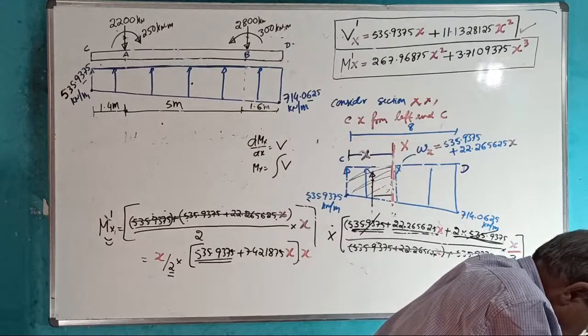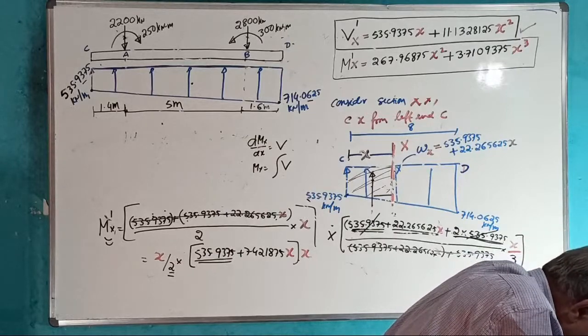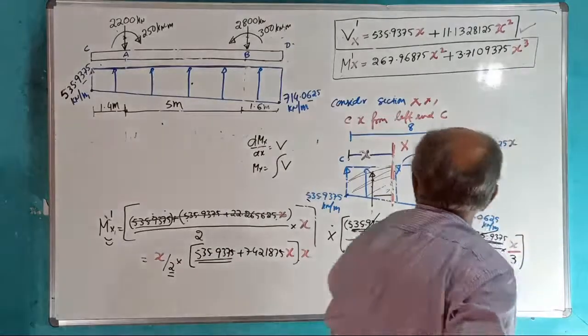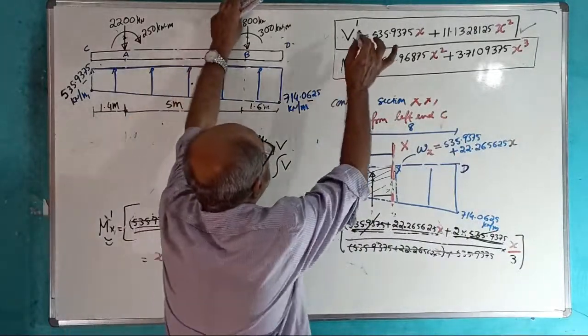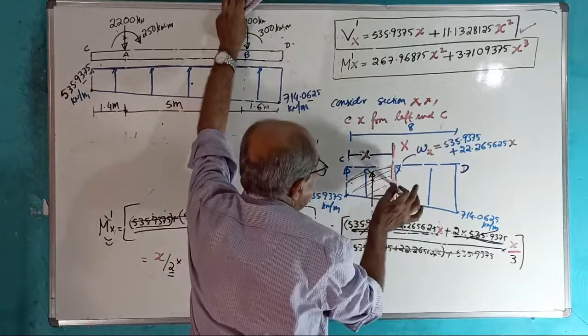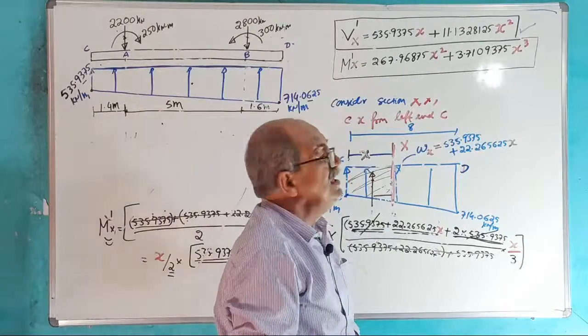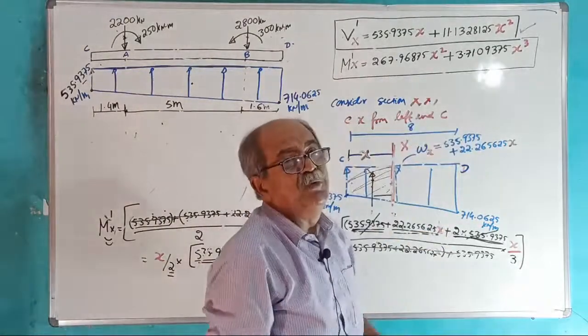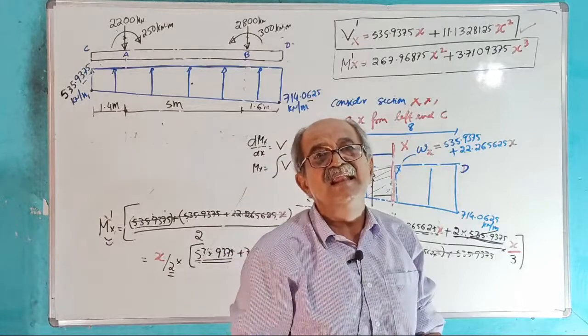Answer, you are not giving. If you integrate that one, are you getting the BM equation? Yes. Therefore, these are all not required. See, shear force you can write directly. Why? Sum of the two sides divided by 2 into X. While doing bending moment, I can tell this, I should have told you earlier. Why am I not telling? You should struggle once, then remember.